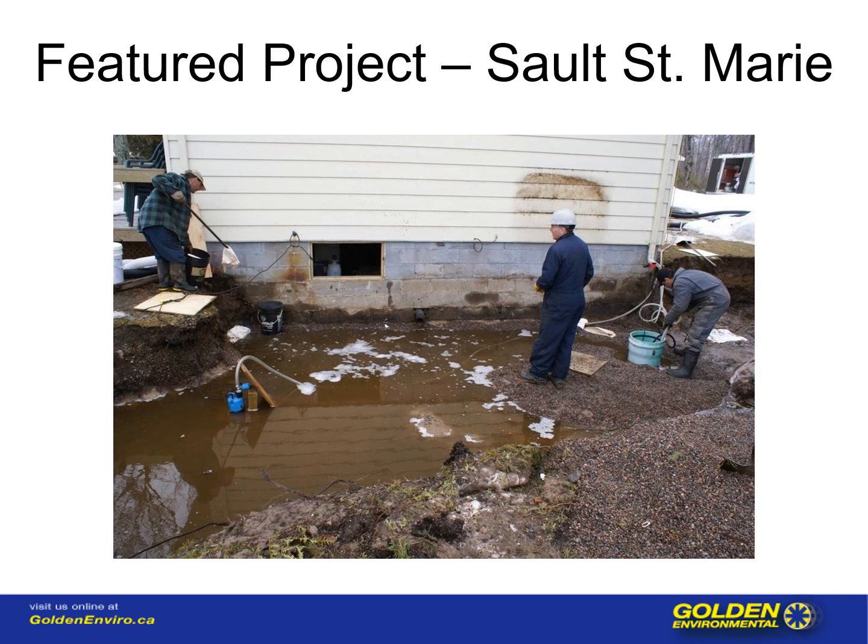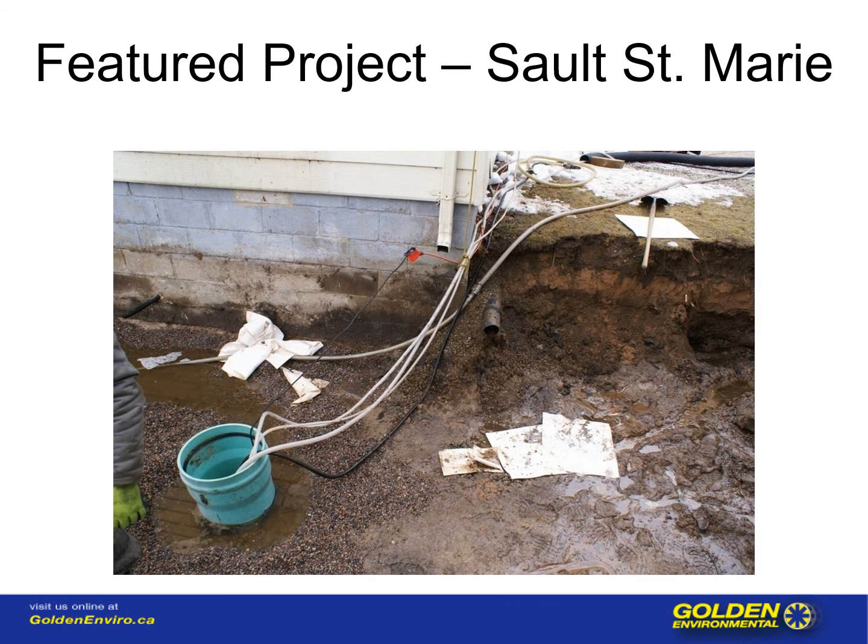Here's a photo along the side of the home. You can see in the right-hand side of the building where that dirty spot is, that soiled spot on the side of the building is where the oil tank had sat. You can also see how shallow the groundwater table is and how important it was to establish hydraulic containment very quickly. This is a shot of the recovery well where we established the hydraulic containment. You can see a number of pads sopping up excess oil. You can see how gravelly this area is, so the hydraulic conductivity in this area was exceptionally high.